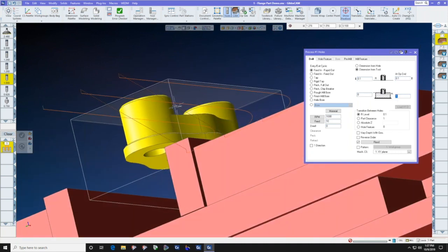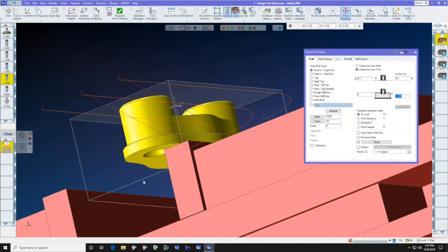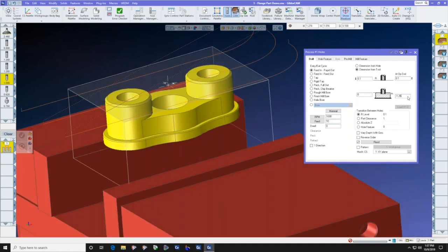If there's another number here and I want that number in there, double click here, alt click the bottom of the part. Now we do need to add a little bit for the radius of the insert. So I'm going to say -0.05 equals. Yes, remember that every field in GibbsCAM is a calculator. Add, subtract, multiply, divide. Okay, our level's 0.1.